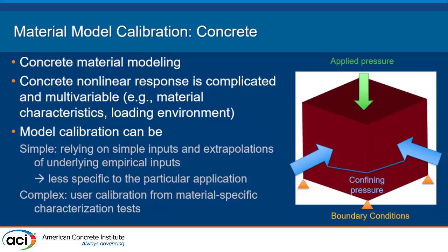There's different models that I tend to use. Some have empirical data in it that you could supply, pretty basic inputs, and it will extrapolate to different conditions. Sometimes that's okay. Oftentimes it's not. Always have to understand the shortcomings and what empirical model is in there that it's extrapolating from. And then as needed, if we need more and more precision, we'll have to get in there and specify all of the 100 parameters that a concrete model needs, and we'll have to have test data to characterize that concrete at different confining pressures, for example.